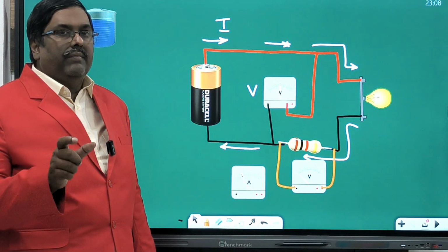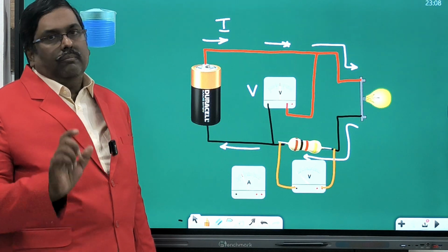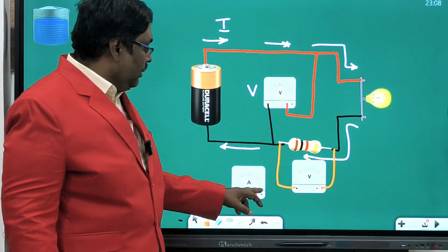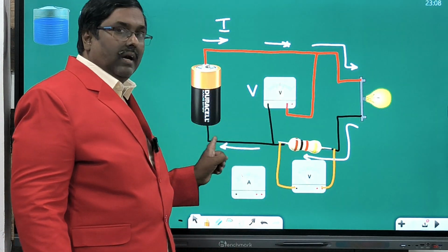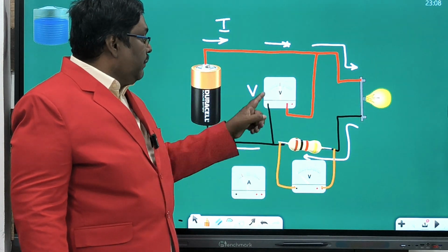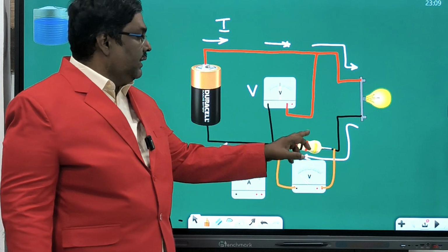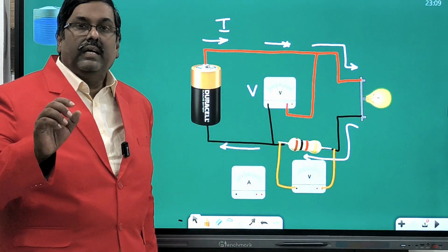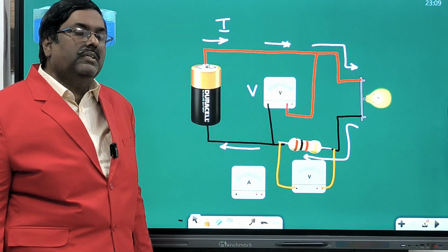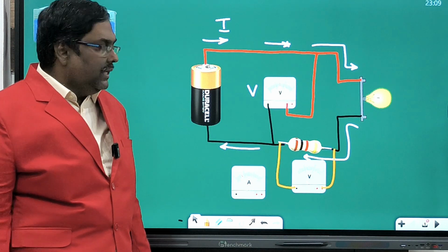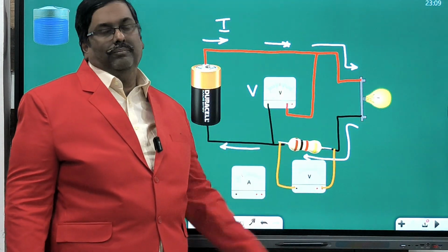So a multimeter will give different terminals for current and volts, because the current meter has a resistance inside. We have to pass the supply through the current. Right? But if by mistake, instead of putting a resistance, you directly put the voltmeter here, the voltmeter resistance is very low, it will not hold. The voltmeter will get damaged. So a voltmeter in series you cannot put. If you want to, you put some resistance and put the voltmeter across the resistance.